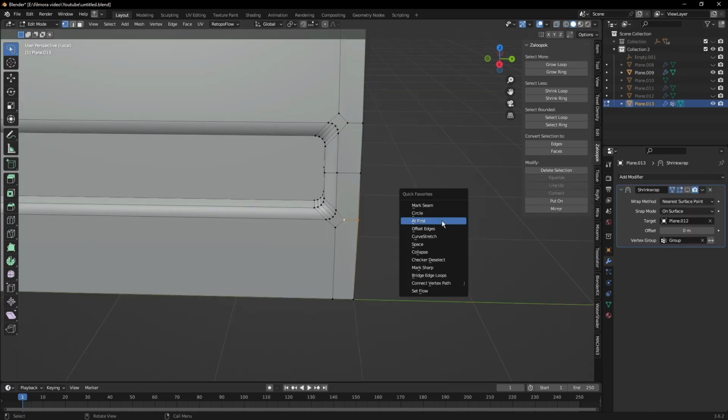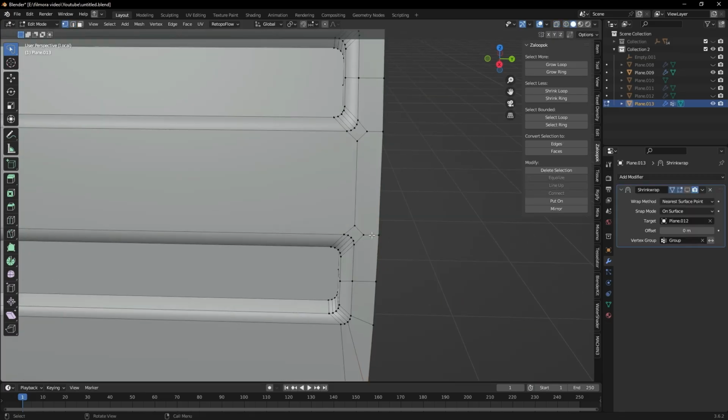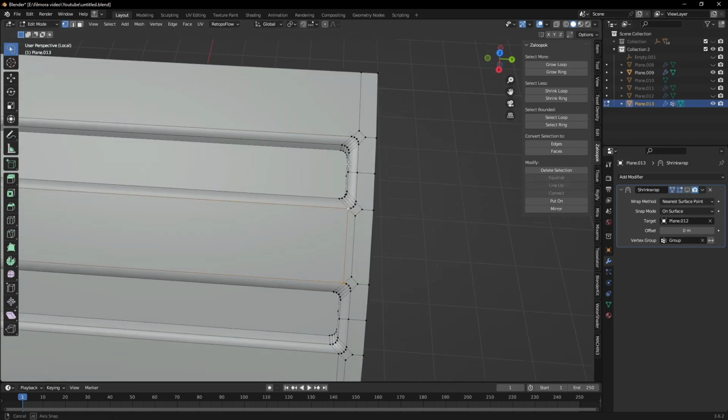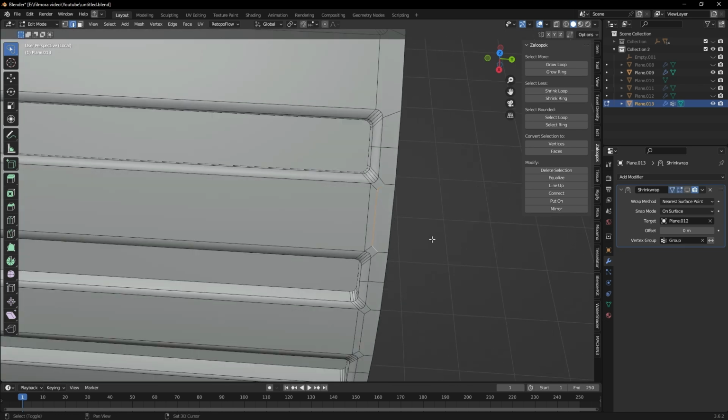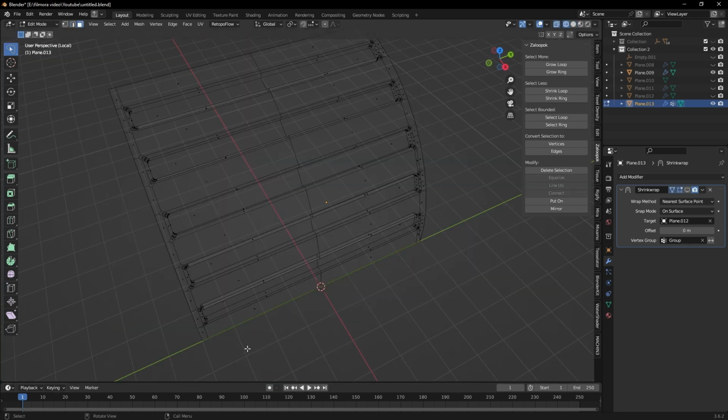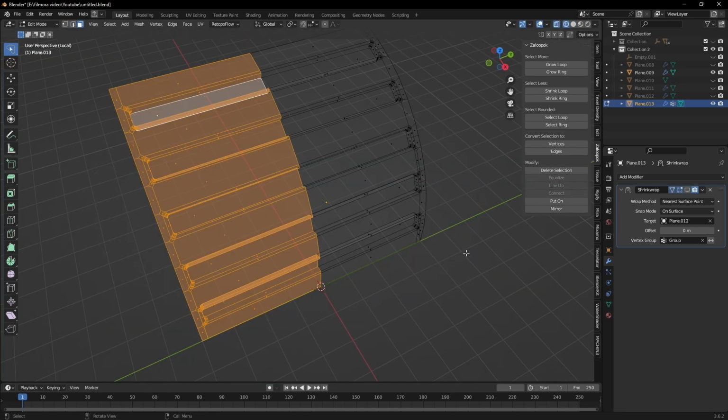Cleanup and curvature. Do a targeted n-gon cleanup. You don't need to resolve every n-gon, but for clean shading and reflections, extend a few loops to the border edges. Work on one half with mirror to go faster.